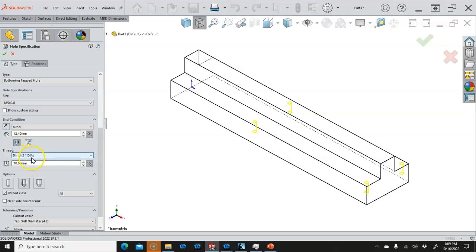If we want 10 millimeters on the thread, as a general rule, would like to have 2 times the major diameter of the threads. Could be as little as 1 time. And then the spiral point tap, a standard tap, is probably going to have 4 to 5, maybe 3 to 5 threads for the lead, which times 0.8 is going to be about 4 millimeters.